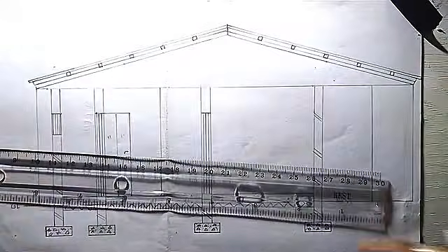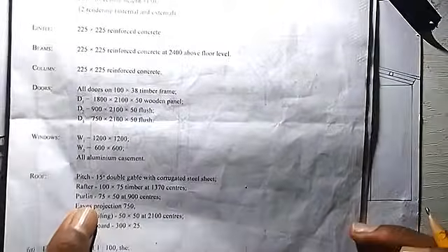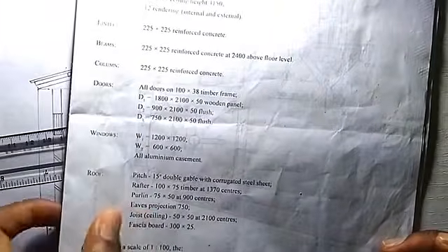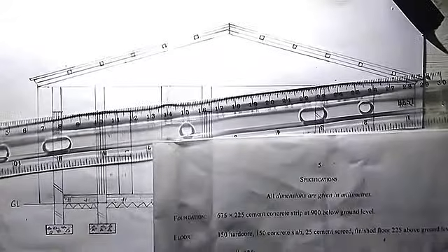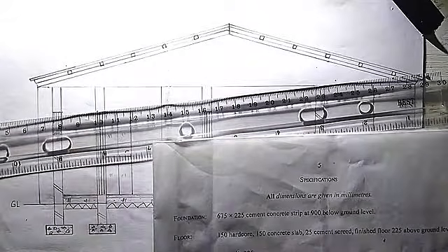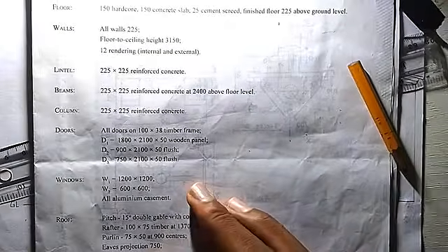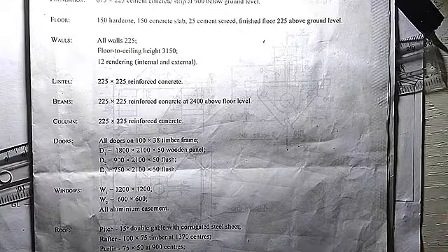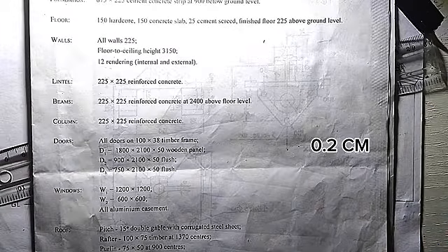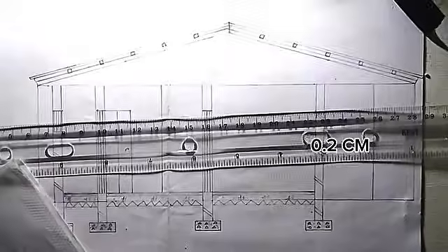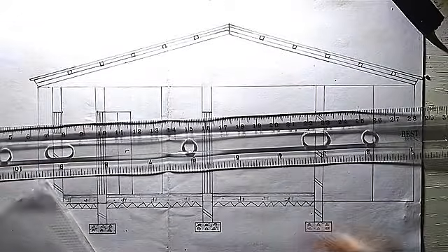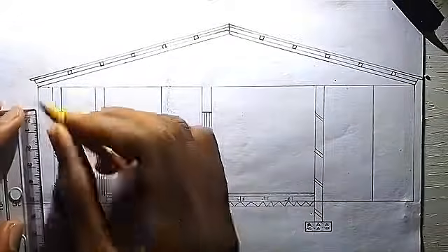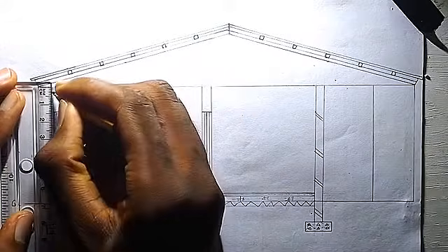Then after the roofing sheet, we have our eaves projection, which is 750. For the eaves projection, we use our wall plate to get that, but the wall plate is not indicated here. Using the 2023 past question, we have everything we need. So this one is better. The specification is easier to understand than the 2024 past question. So the wall plate is 100, which is 100 divided by 50, giving us 0.2 cm. So we mark our wall plate here from this ceiling height. We mark 0.2.